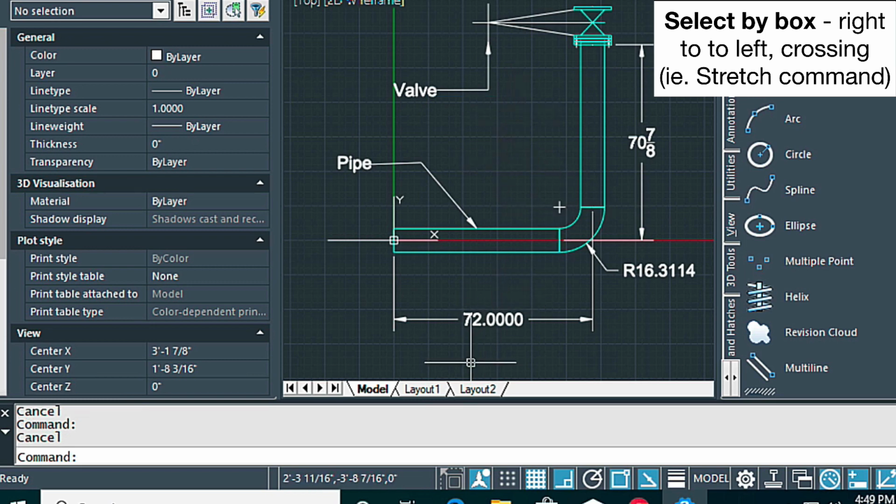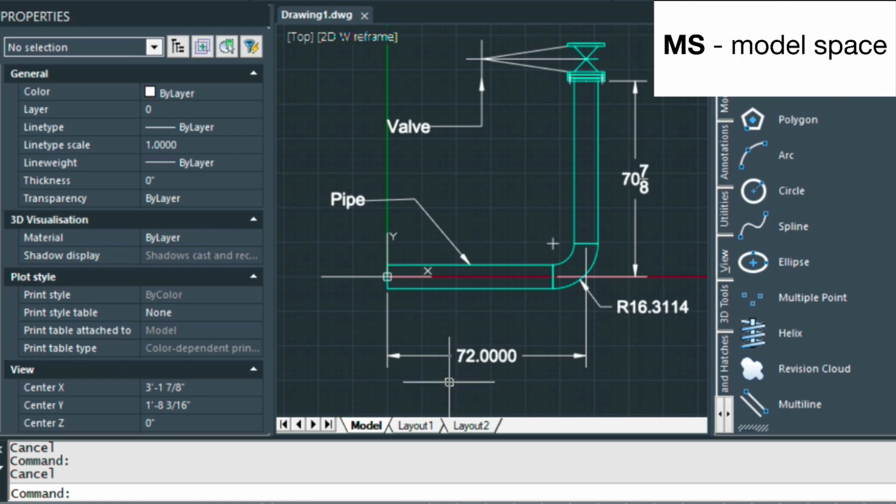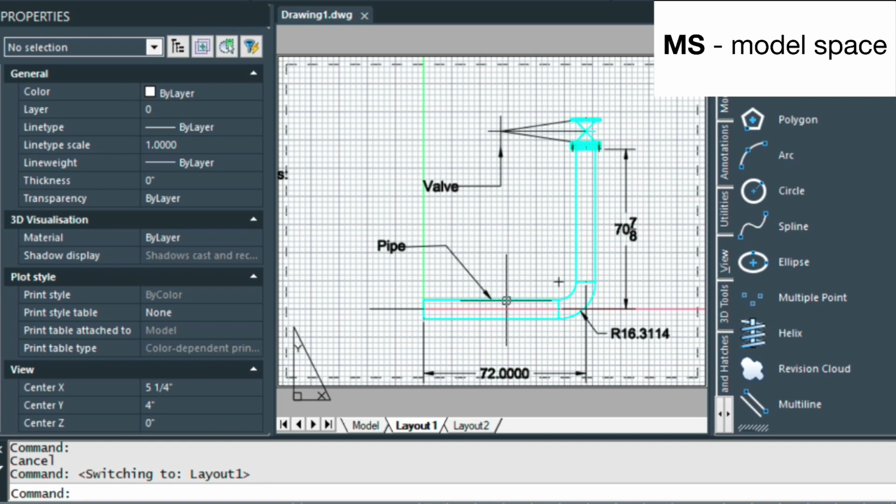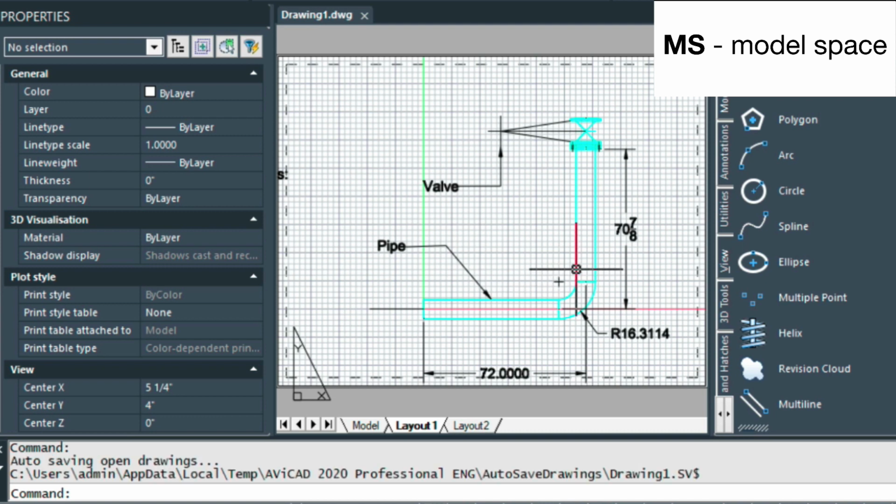Now let's get into a little bit about paper space. Go back to that. As I mentioned earlier, these styles that we created are all based on the paper size and the plot scale. Now adjusting the scale of this paper or the plot can only be done by activating model space within paper space.